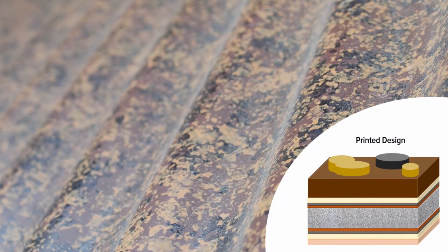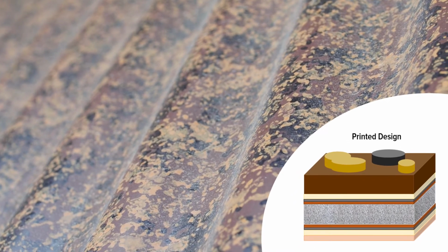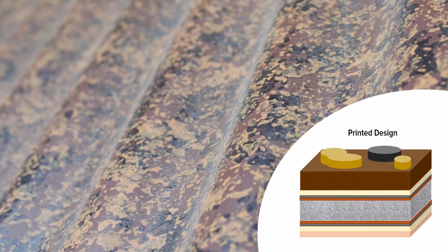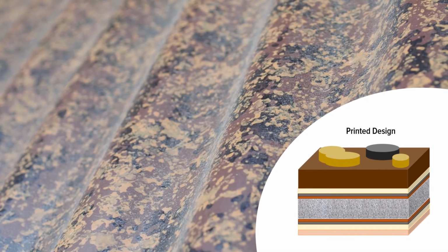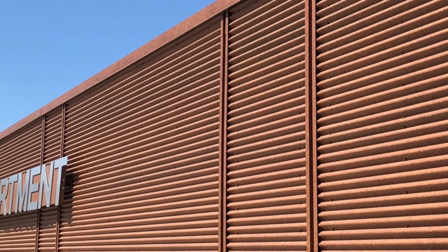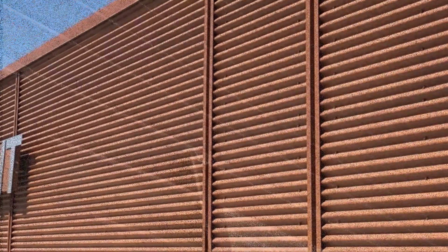The continuous pre-painting production process can be modified in a number of ways to produce more than just solid colours. Printed designs can be achieved by applying an additional one or two layers of paint over the base coat using a pre-developed design, for example wood grain, brushed steel or granite. The base colour on these designs is a solid colour like a traditional metal finish. The design is achieved by having specialty applicator rolls pre-etched with a design, roll the design pattern onto the metal in a similar way to a printing press. Applicator rolls can be modified to recreate a range of designs.